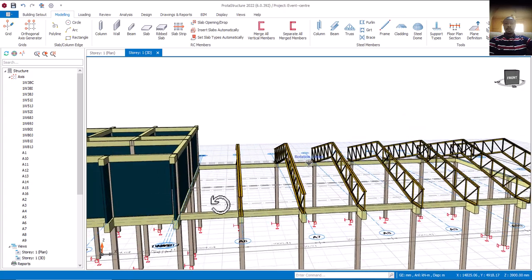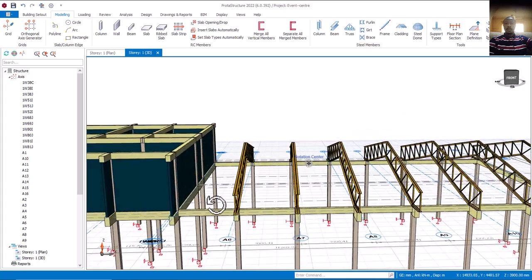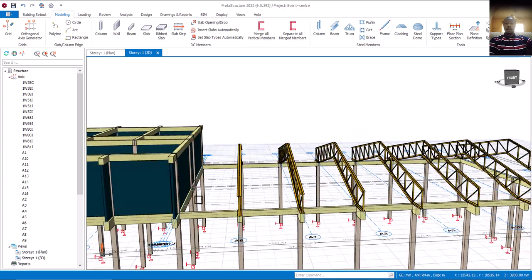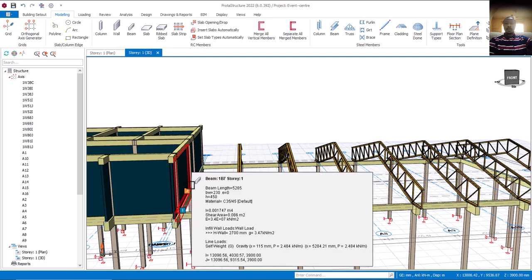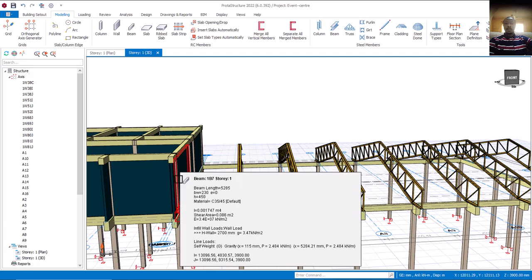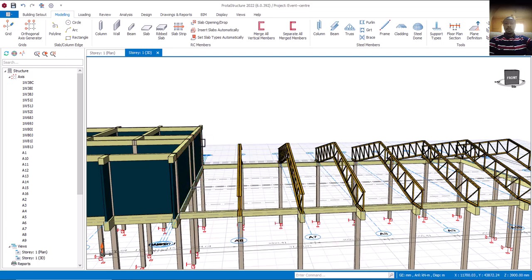It depends on you, but in this case, I'm going to provide another truss here, close by, so that even though the purlin is going to extend maybe just 75 mm or at most 100 mm into this wall, understand? To avoid water entering through this place, the space between the roof and the wall. All right, that's fine.